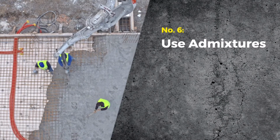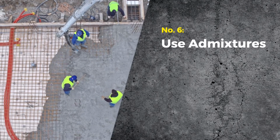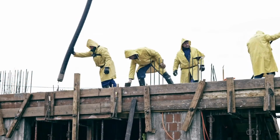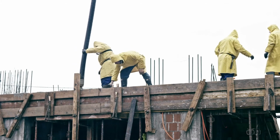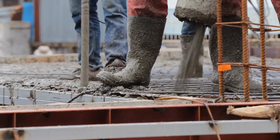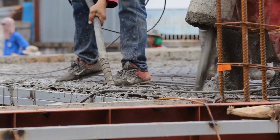The next strategy is to use admixtures. Nearly every concrete made today uses some sort of admixture. Most affect the plastic properties in order to make concrete more workable, economical, shorten or lengthen set time, and so on. Without admixtures, concrete could not be pumped hundreds of feet in the air or transported hundreds of miles, and many architectural finishes could not be achieved. There are water-reducing admixtures that in effect reduce cement demand, accelerators that improve strength gain, and viscosity modifiers that permit concrete to flow into very tight spaces.